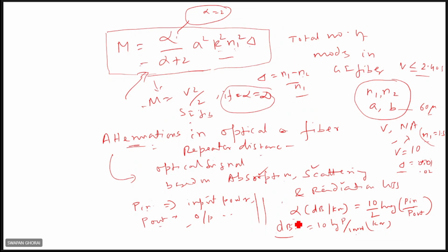This is another important parameter of optical fibers. So we have seen numerical aperture, one important parameter, and V number. Now alpha is another important parameter. Actually, when you procure the fibers, if you want to use the fibers, these three are most important. Of course, bandwidth also is there. The V number will identify the type of fiber, say it is a multimode fiber, but then you also have to see what the bandwidth of the fiber is. So these are the important parameters while dealing with fibers, and these are important relations concerning attenuation.